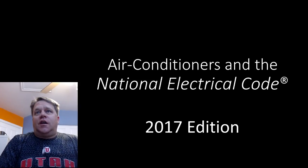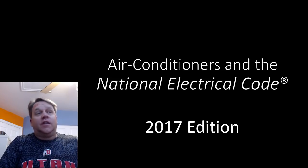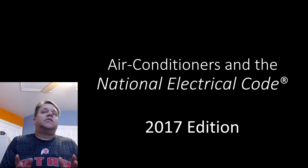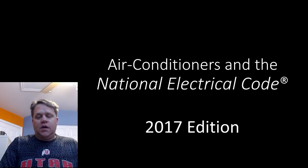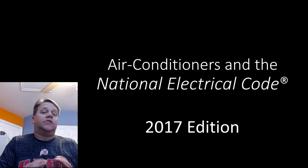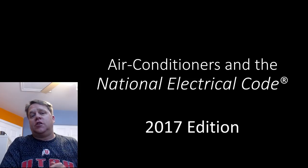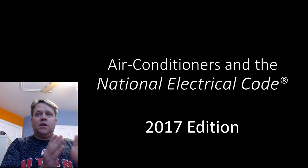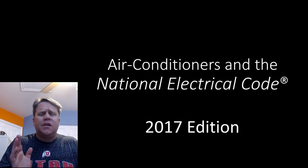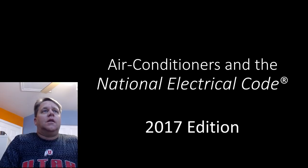Hi, thanks for watching. I've been asked by a few people to cover air conditioners and the National Electrical Code, and it's kind of funny because air conditioners are actually, and I mean this, the easiest circuit in the entire code book, believe it or not. The rules in the code actually require that the manufacturer does all the calculations for you and tells you the answers, and then all you as the electrician have to do is read the nameplate and install the conductors and overcurrent protection. So it's a remarkably easy circuit, but it's very misunderstood as well. So we're going to be covering that today.